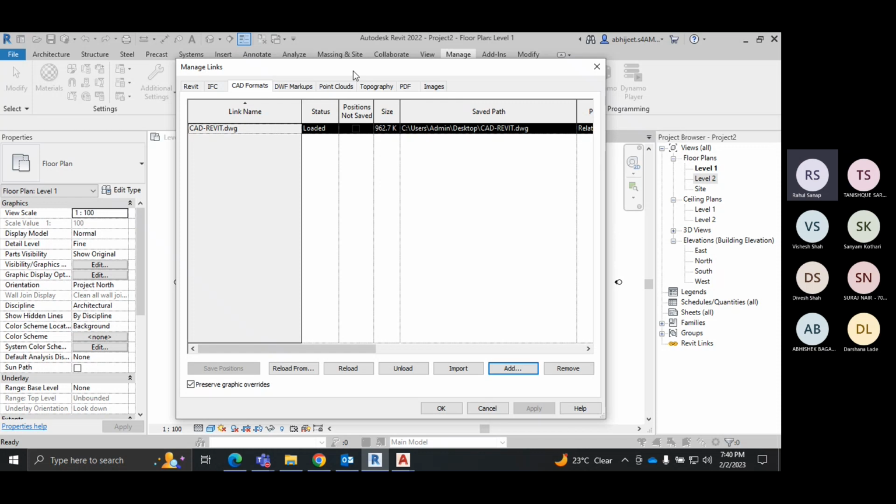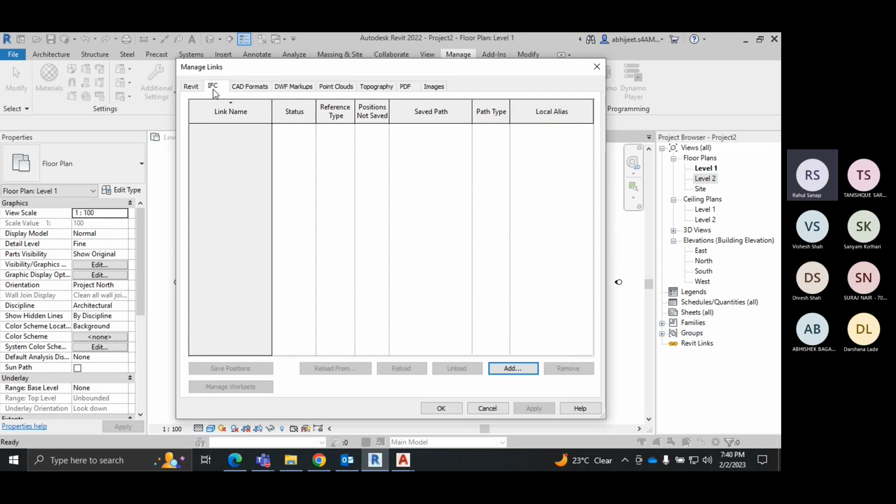Okay, so I recently told you what a linked CAD is. Linked CAD means that particular file will be linked with the original file. So let's say person X is making some changes and I want to see those new changes inside my Revit model. In that scenario, I simply click on the file and say Reload, because the path is the same for me as well as for the particular person who is working on that file. If you click on Reload, all the new changes will automatically be visible in your Revit model.